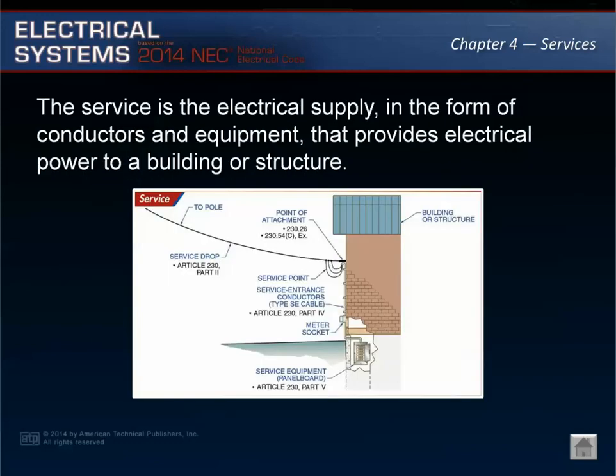The service is the electrical supply in the form of conductors and equipment that provides electrical power to the building or structure. Note that the source of supply for the service must be from the utility. Service is the root word for 8 other terms that are defined in Article 100. It is a general term and usually includes the underground service or overhead service conductors, service equipment, and any associated metering equipment.